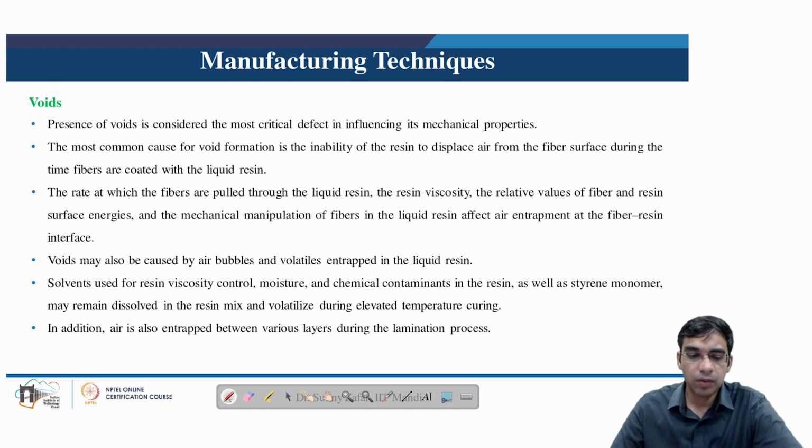matrix. The most common cause of void formation is the inability of the resin to displace air from the fiber surface during the time fibers are coated with the liquid resin. The rate at which the fibers are pulled through the liquid resin, the resin viscosity, relative values of fiber and resin surface energies, and the mechanical manipulation of fibers in the liquid resin affect the air entrapment at the fiber resin interface. Voids may also be caused by air bubbles and volatiles entrapped in the liquid resin.